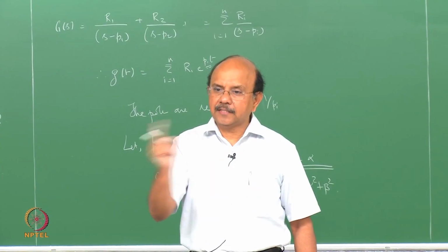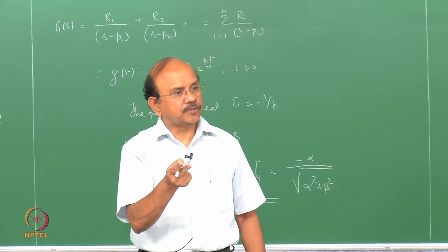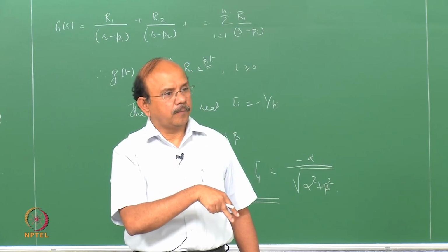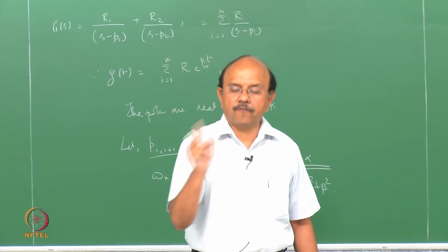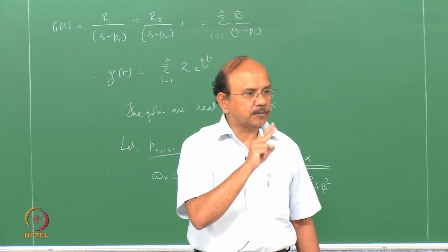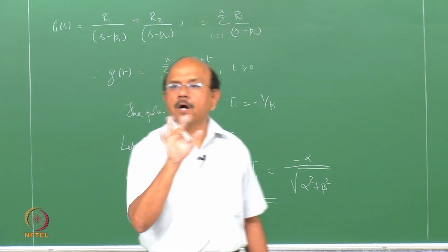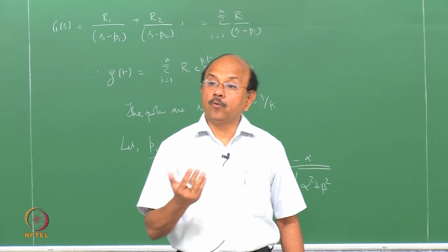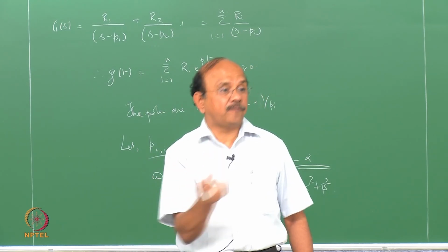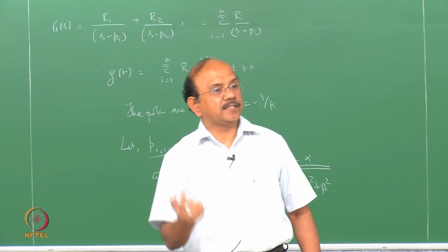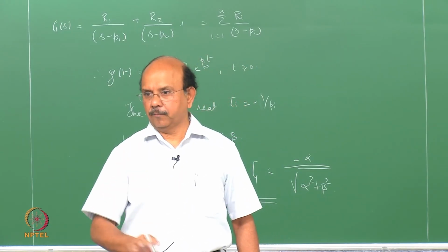We had taken minus alpha F so that ultimately that equation becomes plus C alpha F. Sorry, we've taken minus alpha F, and so C alpha F we had kept as positive, so that we get the centripetal force accordingly. But there are people who have written alpha F to be positive and C alpha F to be negative, in which case their K definition would change and so on.